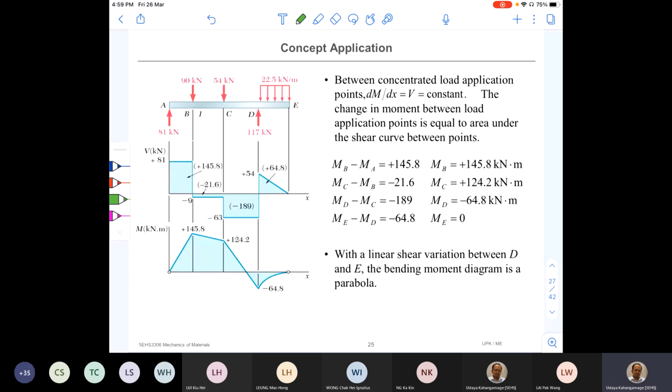So I have moved the same shear force diagram, and now I have constructed the bending moment diagram. To construct the bending moment diagram, what we need is maybe the initial bending moment. If you know key point bending moments, then we can construct the remaining distributions easily. Now, point A is a simply supported point, right? Therefore, at that point, there's only reaction force, no bending moment. Bending moment is 0. So this is MA.